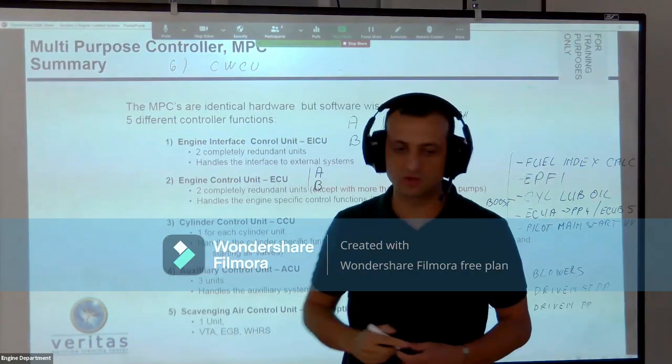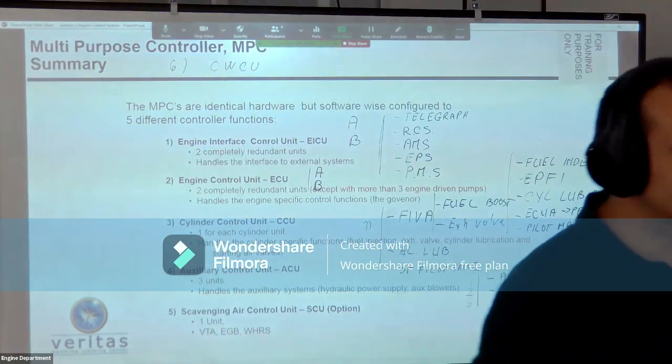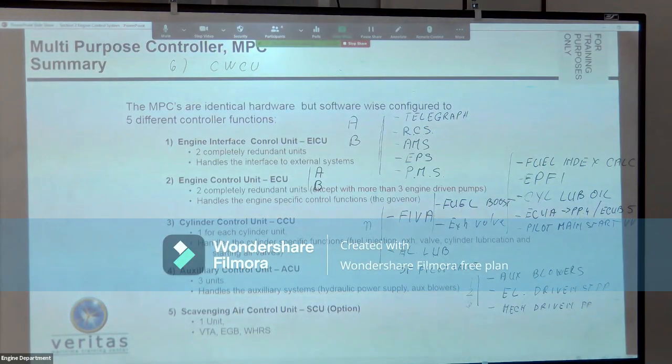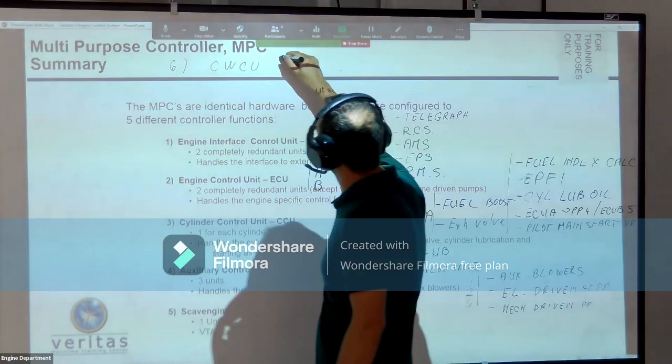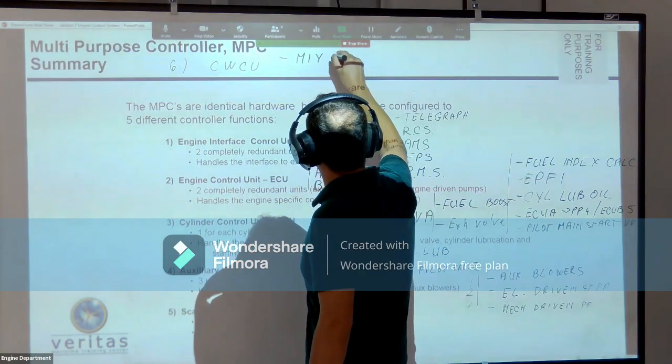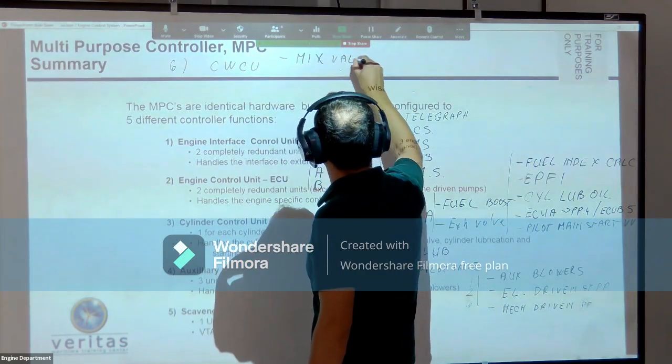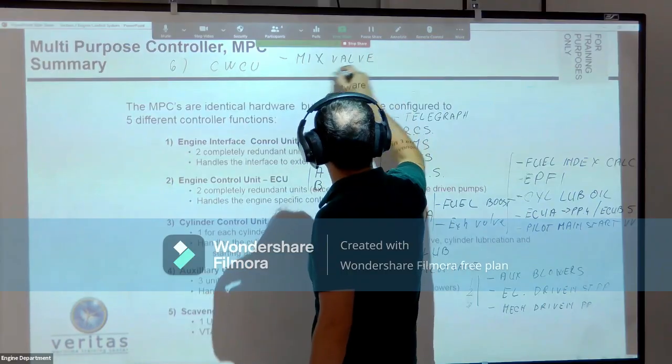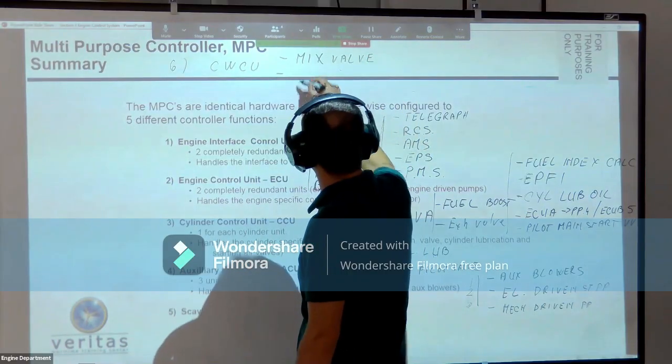Its role is to adjust the cooling water temperature in the jacket area according to the engine load. During low load operation, below 50% engine load, the set point is 120 degrees. This equipment is controlling a mixing valve and circulating pump.